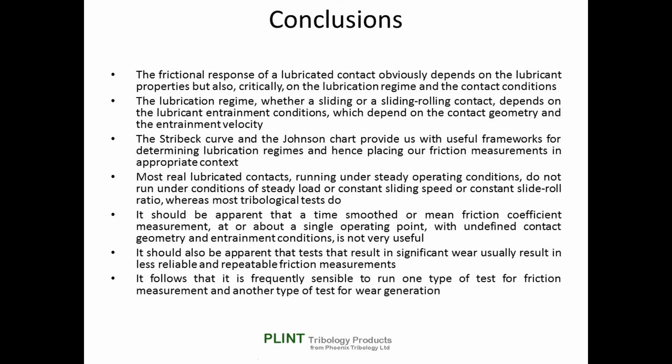The lubricant entrainment conditions depend on the contact geometry and the entrainment velocity. The Stribeck curve and the Johnson chart provide us with useful frameworks for determining lubrication regimes and hence placing our friction measurements in the appropriate context.